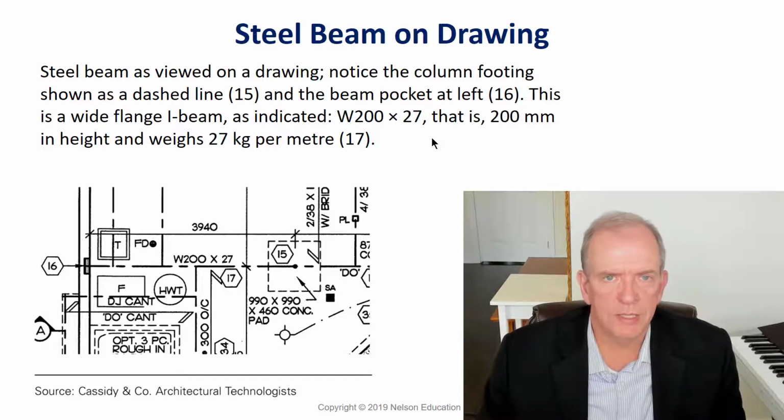If you want to go customizing in extra spans that are beyond Part 9, then you hire an engineer and they will do the calculations based on Part 3 of the building code and provide a beam size for you.